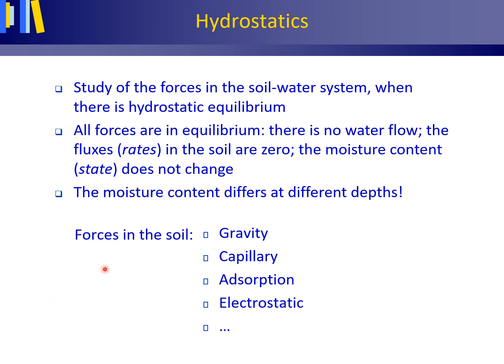The forces in the soil, to name a few, are gravity at high water contents in the soil for the larger pores, capillary forces, especially when the soil is dry in silt or sand. Adsorption, this is a process whereby soil water accumulates on solid soil surfaces, forming a thin molecular film of water when the soil is dry. Electrostatic forces in clay, osmotic pressure in saline soils, etc.